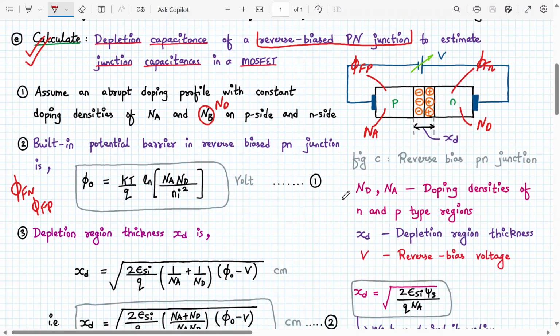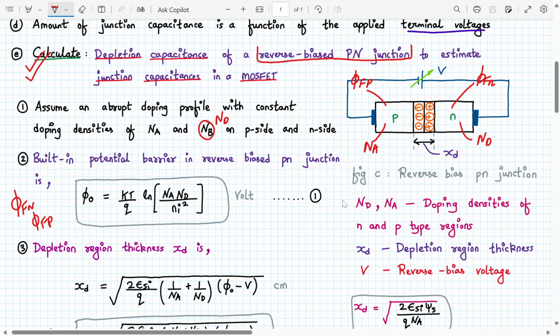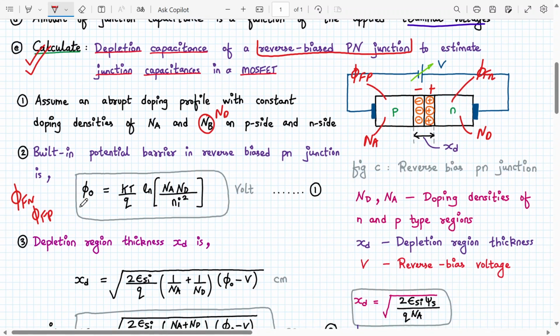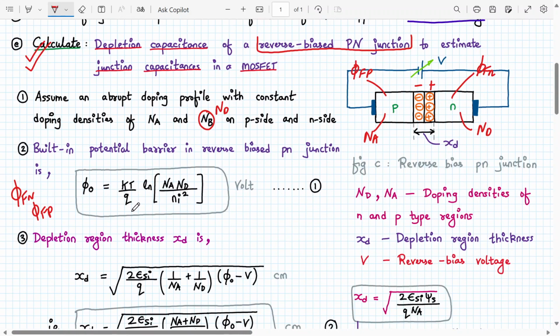Okay, so somewhere related to that, but since there is a depletion layer present over here, there are charges present, and whenever there are charges present, there will be an electric field because of the built-in potential. So here we have a total built-in potential as negative to positive this way. So there will be an electric field directed. So this depletion region potential is called phi naught, KT by Q natural log of Na Nd upon Ni square. So this is step number 1.